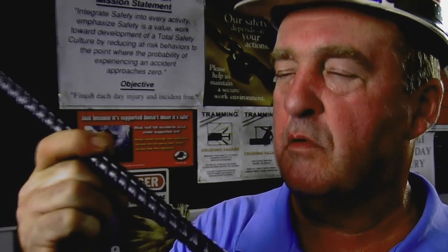The purpose of a roof bolt is to hold the roof up. It's as simple as that. The most common type of roof bolts used in a mine are fully grouted resin bolts. We have tension bolts, and we also have cable bolts. This is a number 5 rebar. It's a fully grouted bolt. It's also one of the most misused bolts in the industry, and I'll tell you why.